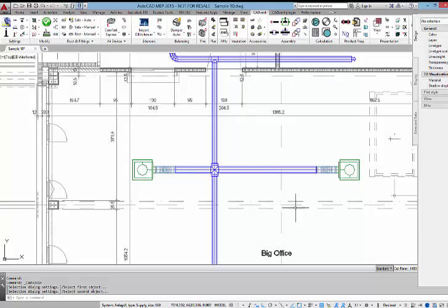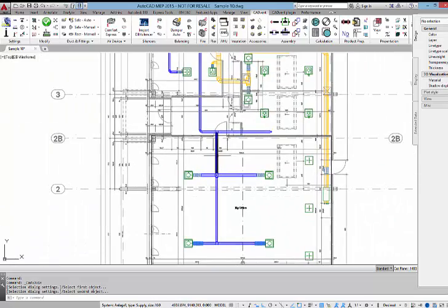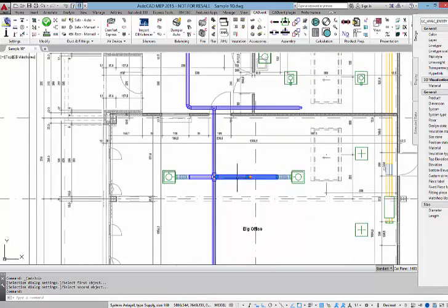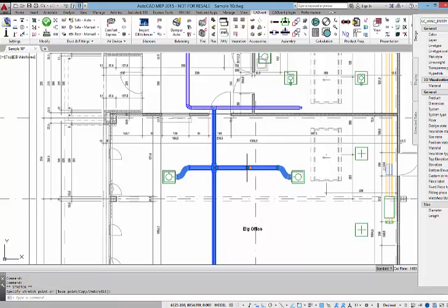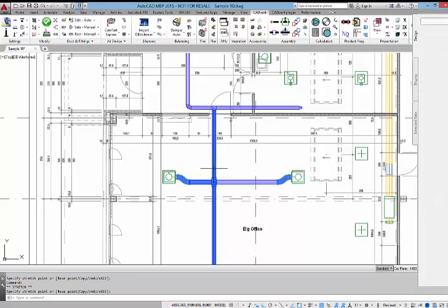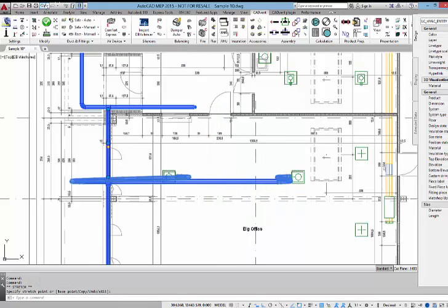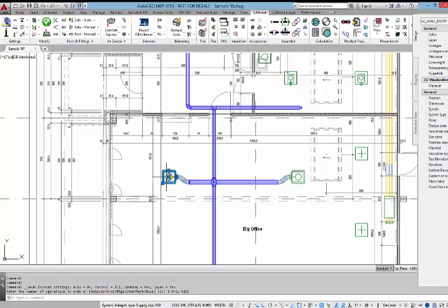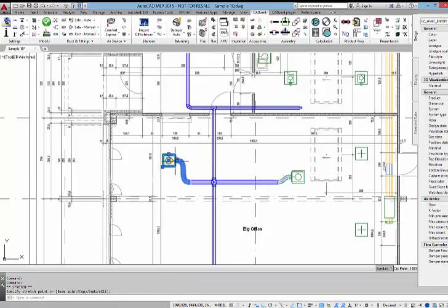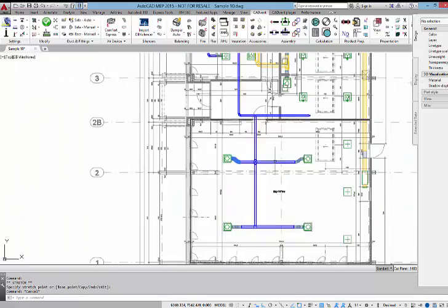So it's rather fast to design in CADvent, to move things. And as I mentioned already, it's simple to move components. It automatically uses the flexibility in ducts because the length does not fit here. And flexible ducts are fully flexible. A flexible duct will automatically be used flexibly. So same when I move the device, the flexible ducts will automatically be adjusted.